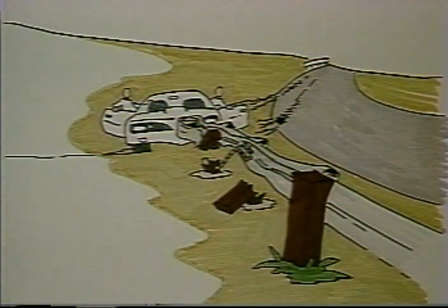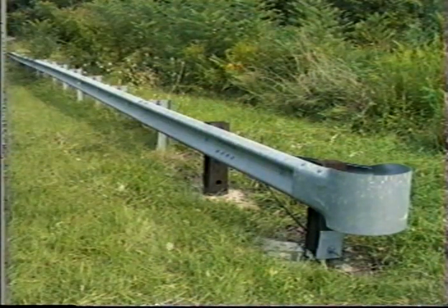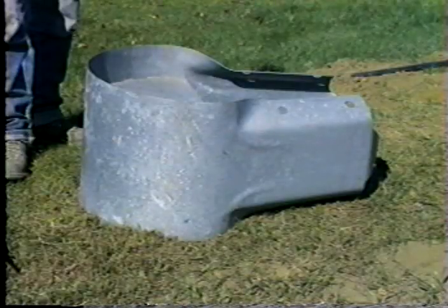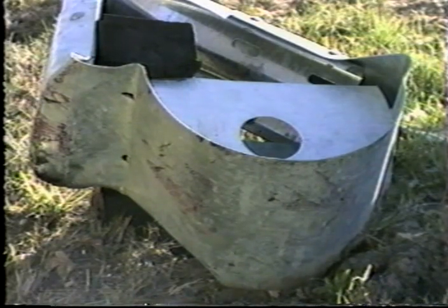When the system is impacted on the end, the wood post breaks away. In the steel post system, it slips away. And this action releases the tension in the cable, allowing the W-beam to buckle. Depending on the size, weight, and speed of the impacting car, beams in the end treatment continue to buckle until the vehicle is stopped. A bulb on the front of the system is intended to distribute a head-on collision's weight and force. It flattens out, preventing the W-beam rail from spearing the impacting vehicle. Here's a new bulb just prior to installation, and one that's been hit and done its job.